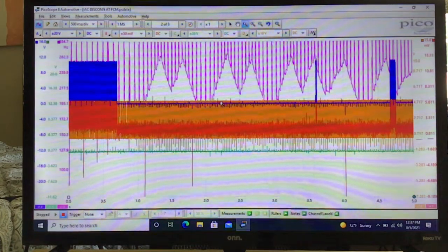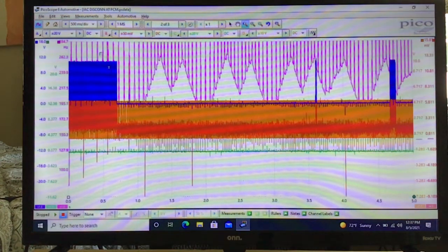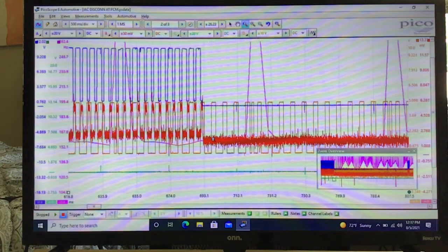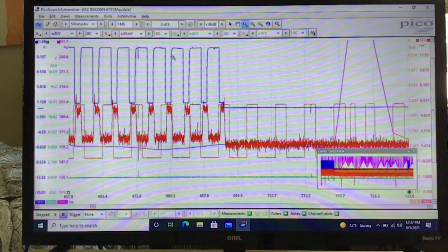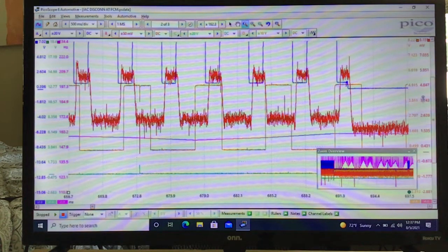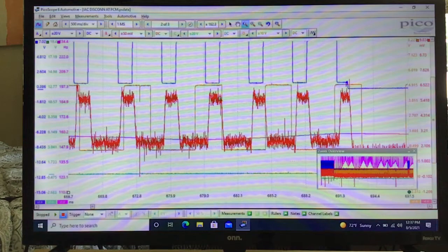This is before it gets disconnected. We'll key in on this. It tells us a lot about voltage and current. Here's our voltage and current, before I disconnected it right here. We're ground side switched, so when the circuit goes low, when the driver closes at the PCM, that's when current flows. I'll stretch that so we can see the relationship between voltage and current. It's pretty clear how much we're drawing. That is the current flowing.